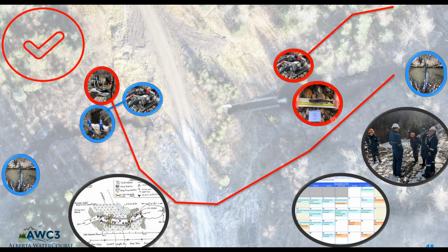Once this is all set up, we are going to dewater and defish our crossing. Again, we have our isolation upstream and downstream. So in this process, we have to make sure we give our biologists time to defish the site, whether we are trapping or electroshocking or netting. We are dewatering through our dewatering pumps.